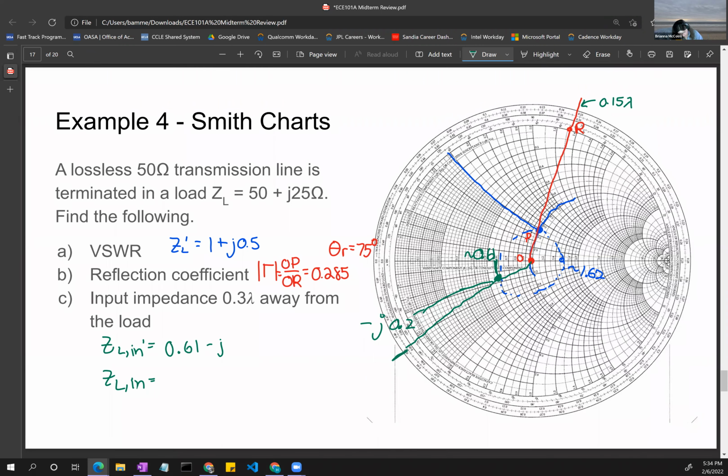Okay, so another important thing that you can do with Smith charts is stub matching. That's taking an impedance where you're looking in at that impedance, and then adding some sort of shunt across that to get rid of some unwanted inductance or capacitance in your transmission line. Typically, you're trying to make your transmission line totally resistive, so you don't have to worry about any energy storing components. So stub matching is a great way to do that, and this is a sort of recipe for how to do that.